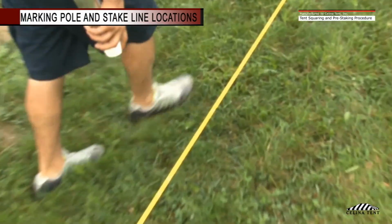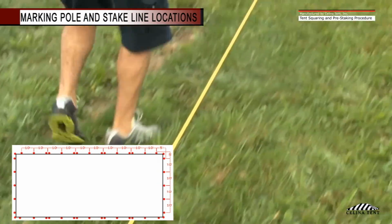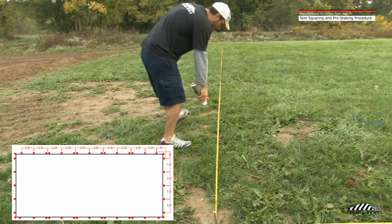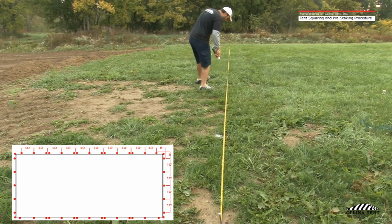Use the white marking paint to identify all corners and side pole locations. The side pole spacing for this tent is every 10 foot around the perimeter. Remember, the stake line is 5 feet, so the first stake position from every corner will be 5 feet in, and then 10-foot spacing from that position.